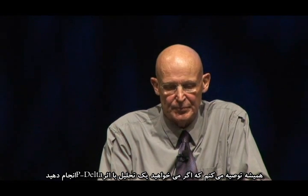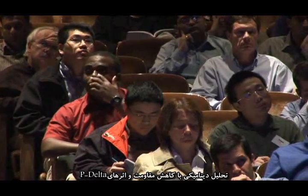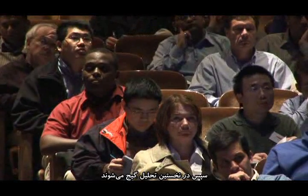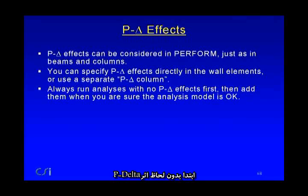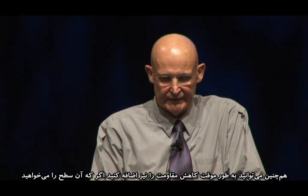And I do always recommend that if you're running an analysis with P-delta effects, then turn the P-delta effects off first, run your model, make sure it's working okay, and then after you're sure it's working okay, turn on the P-delta effects. Because I've often seen people just do everything. The first analysis people will run will be a dynamic analysis with strength loss and P-delta effects, and then they'll wonder why it didn't run the first time. Start off without any P-delta effects, run a static analysis, and also suppress the strength loss. And Perform allows you to do this rather easily. You can turn on and off P-delta effects easily, and you can also suppress the strength loss temporarily if you want to with very little effort.